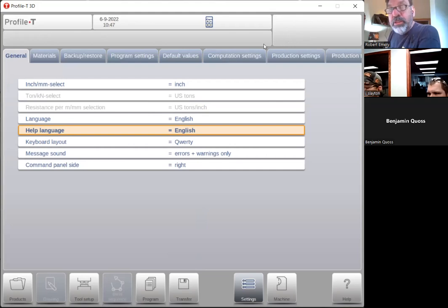So there'll be a little status readout up here with a number from 1 to 6. 1 means idle. So if you step on the pedal and nothing's happening, look at that. If it says 1, then you know it's the light guard or something else. It's not the control. Coming down, it should be a 2 for fast, a 3 for slow. If it doesn't show a 2 or 3, it doesn't know you want it to come down, because the guard is upset. So you've got to correct that.